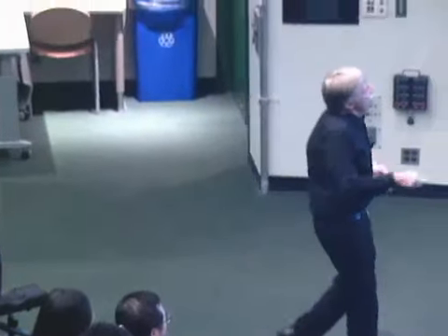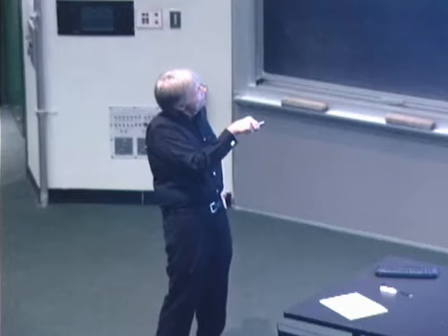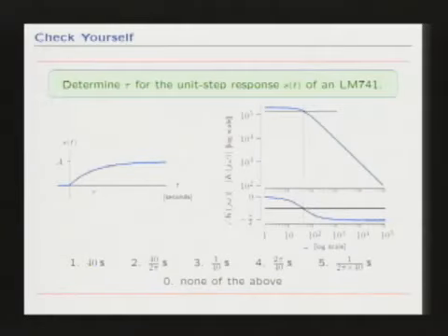And in fact, what I'd like you to do is figure out exactly how it's associated with that phase delay. It will turn out that the step response can be characterized by a time constant tau. The time constant tau is the time required for the signal to get within 1 over e of its final value. I've already told you the performance parameters in terms of frequency. You should be able to use 6003 to figure out what that implies about time.